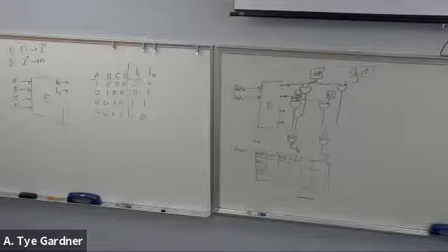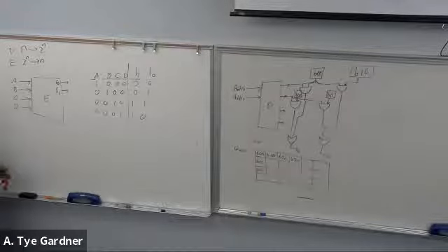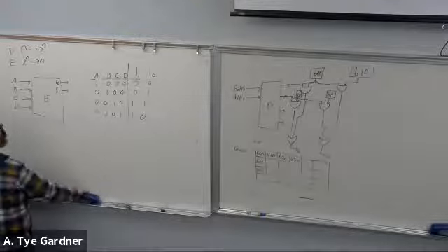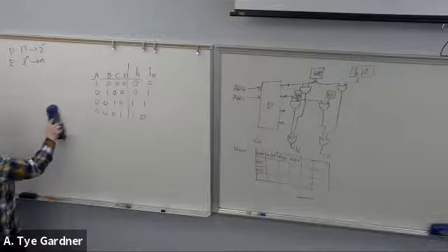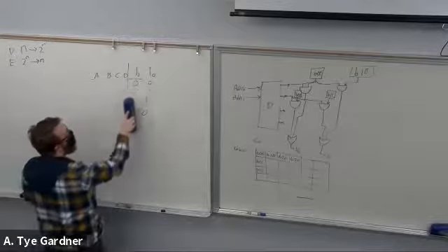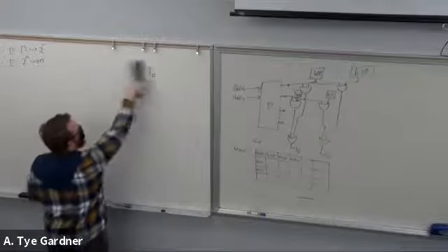Well, that brings us to our next device, which is just code converters. So a lot of people like to think they switch encoder and code converters. So encoders are strictly 1 hot to an address, and code converters are transitioning from one type of code to the other. So for example, gray code to binary.